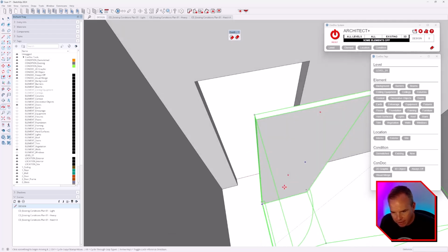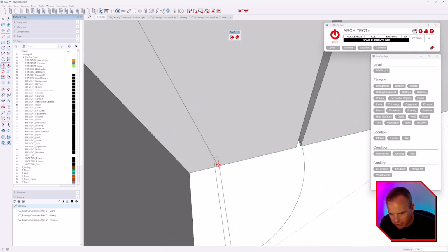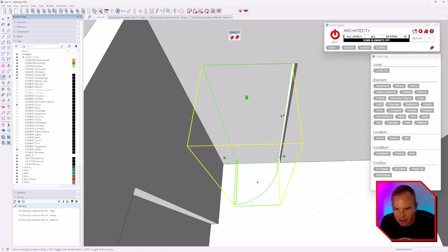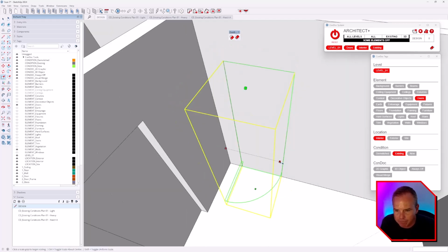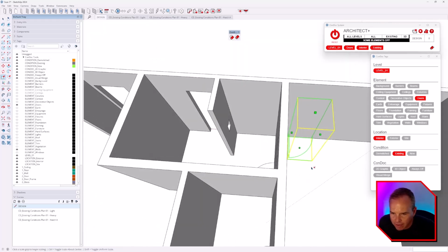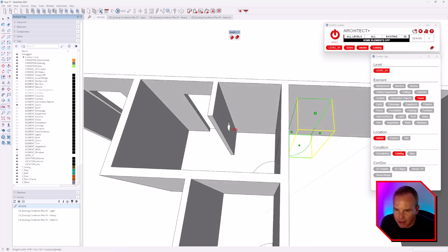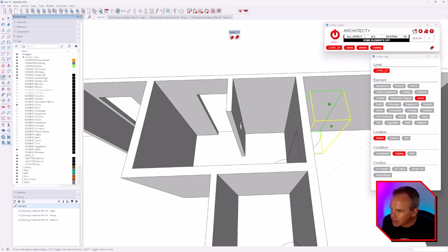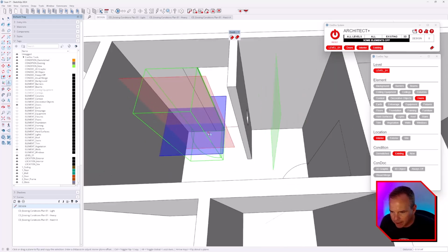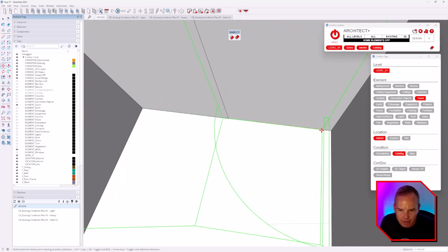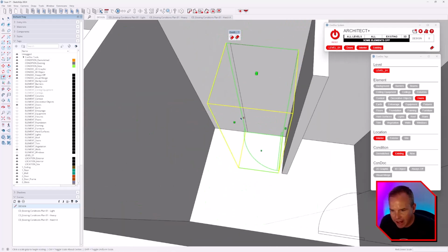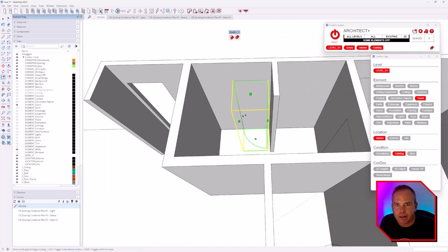And again, it's kind of annoying to have to zoom in to see that. So maybe the default of the ConDoc door should just be a little bit higher, but not a big deal. All right, and then, let's get clever here. Instead of moving it and copying it and then flipping it, let's just flip it and copy it. So I'll tap Control and then we'll just flip it into place. And now maybe I shaved a click or two off by doing that. So I guess that is kind of an advantage of that new flip tool.